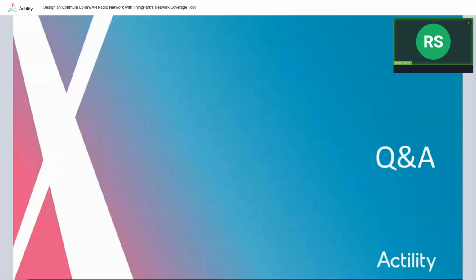Thank you, Alan. Another question: what kind of coverage is supported by the tool? Outdoor, indoor, deep indoor? Can we tune the corresponding level? Yes, actually, that was also one of the things that we have seen later in the demonstration. So several coverage types are supported. It ranges from outdoor to indoor penetrations, going through indoor daylight, what we call indoor first wall, and then deep indoor and even basement for devices that may be located underground, for example. And that's completely tunable in the tool when you launch your simulation.